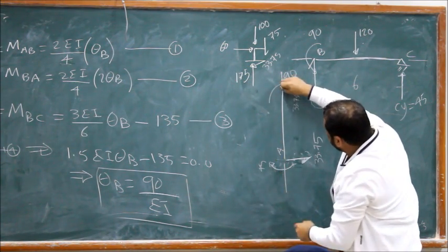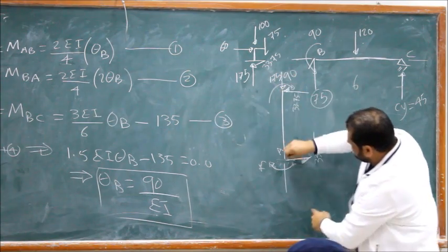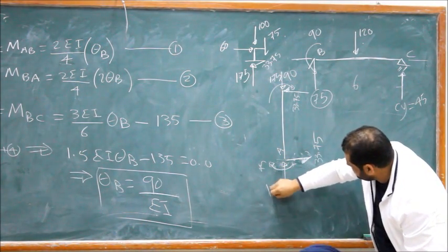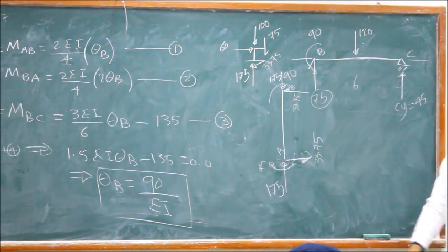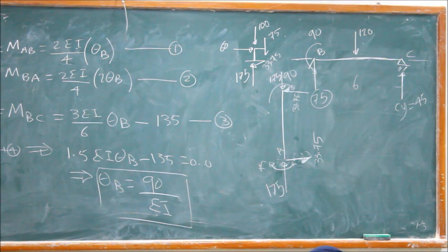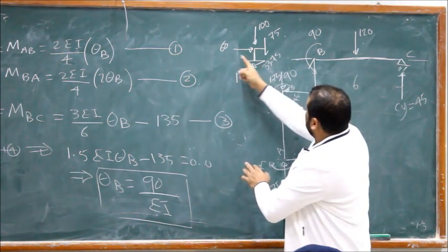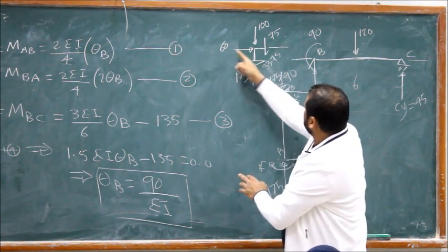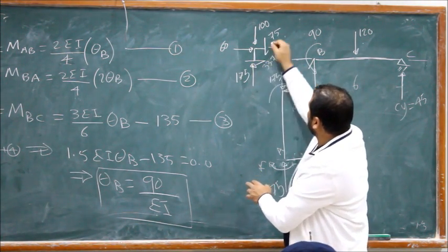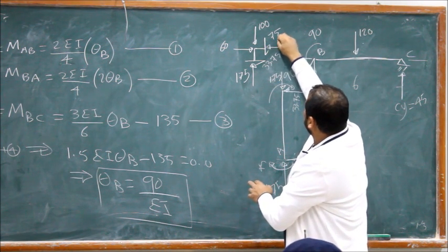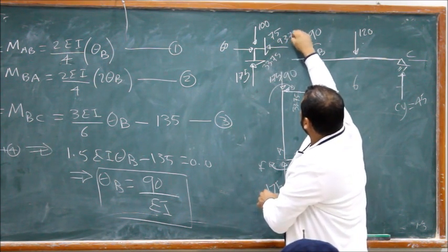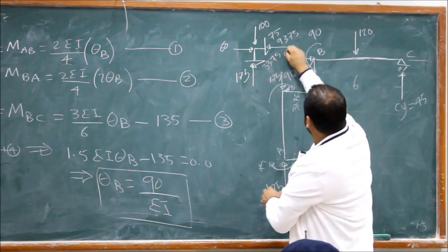So if this is 175 down, how much is the axial force in the column? Good? Now, not done. So how much is this one here? This is 60 and this is 33, so this one will be 93.75, and this is this.